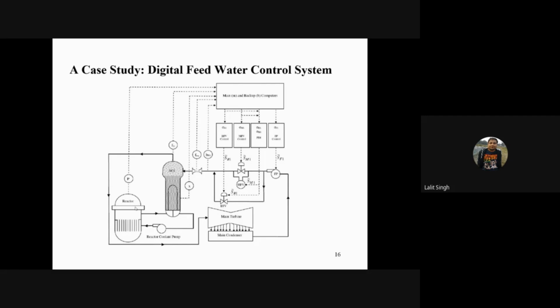There is nuclear fission, and every fission generates almost 220 million electron volts of energy and some 2 to 3 neutrons, and again these neutrons will strike the fuel, which is generally uranium, and then each neutron will be responsible for one fission reaction, and in one fission reaction I get 220 million electron volts of energy.